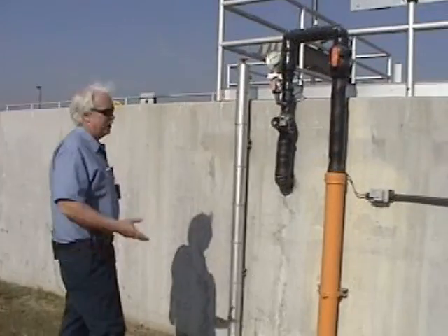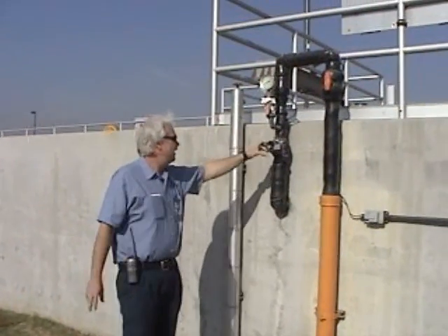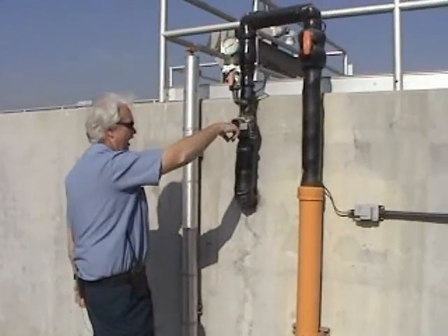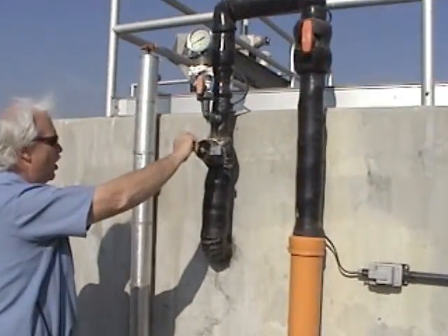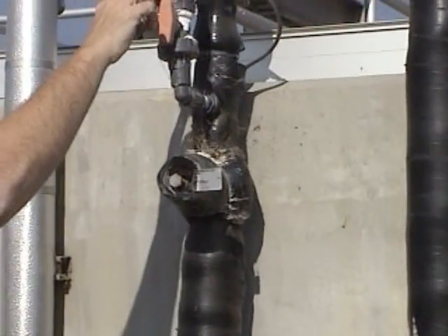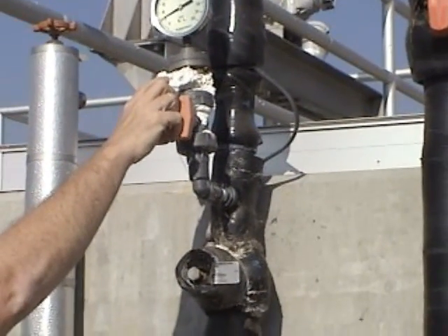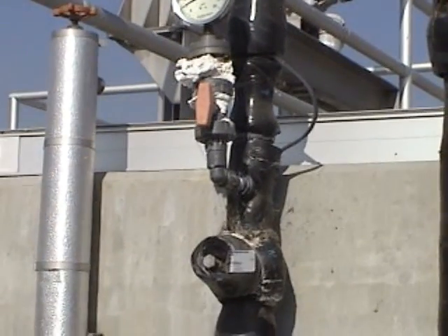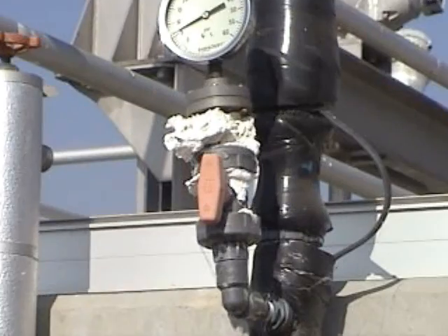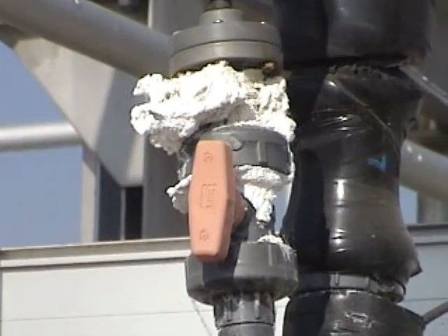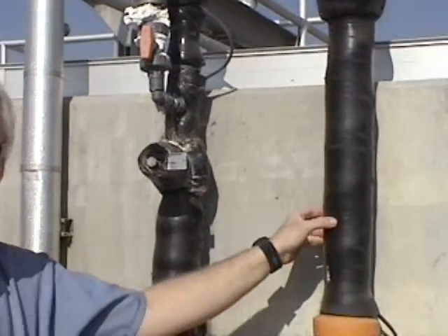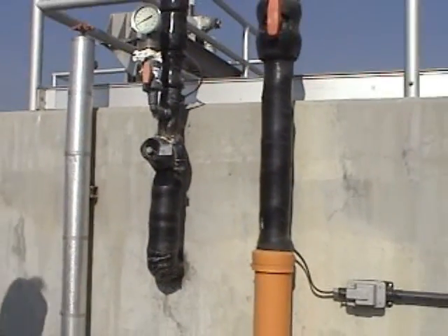If it's running at 60, this is plugged, and one of the things you can do real quickly is get a wrench and run the back pressure knob all the way in and all the way out, in case there is some kind of buildup. You can see where we've had a little bit of leakage here. This crystallization may be on the inside of the valve or the inside of the back pressure valve. By opening and closing this, you can kind of work the crystallization out of the line. It's heat taped to keep it from crystallizing, but it can still happen.